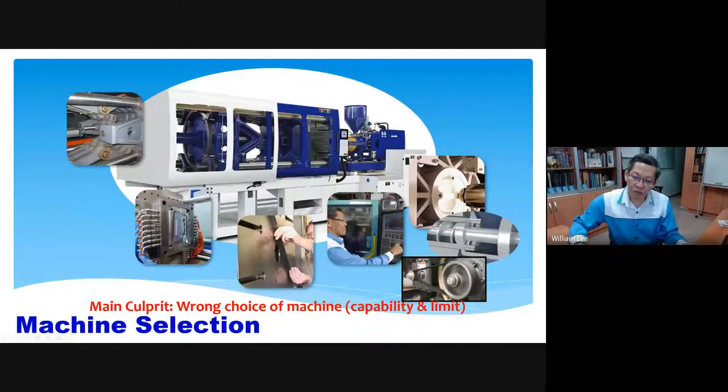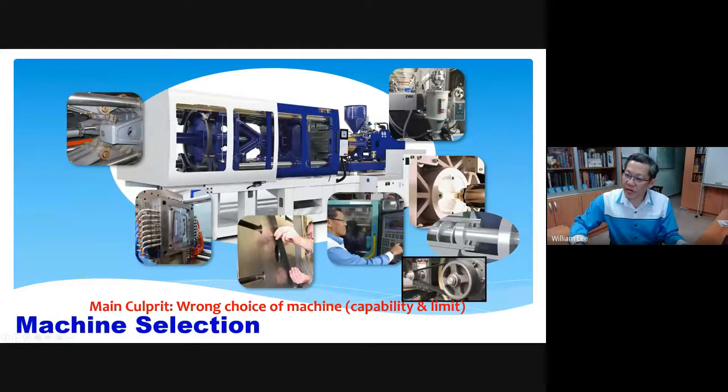And also the mold system involves the cooling system and the hopper drying system, right? So study of the machine specification is important, right? Therefore, when you purchase a machine, usually the machine supplier will give you the full list of the machine specification, involving the clamping tonnage, the power ratings, the shot volume, the control system, dryer system, and also the cooling system.